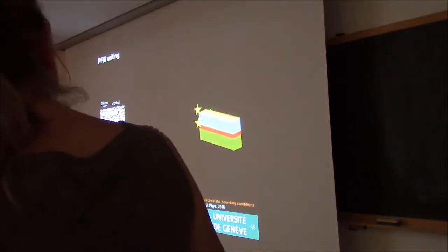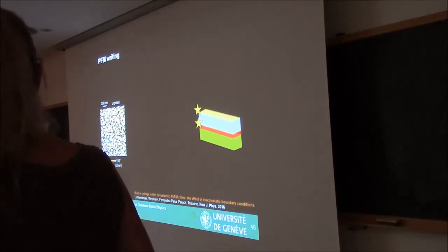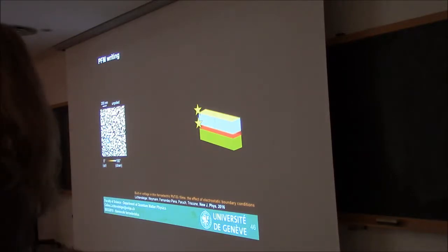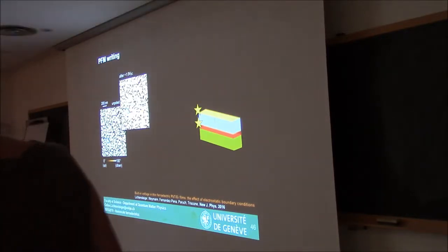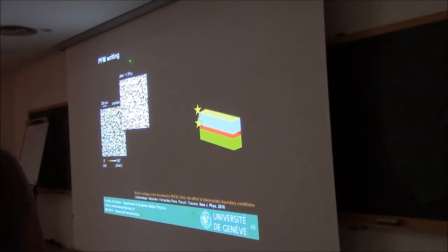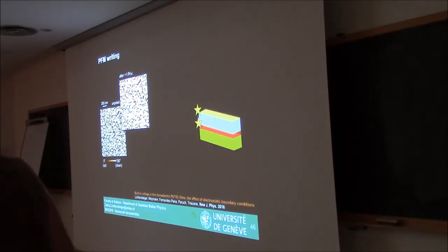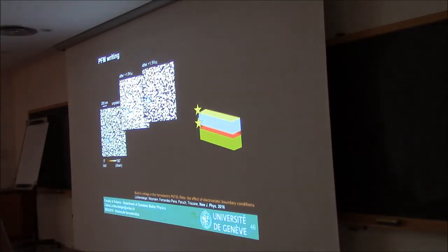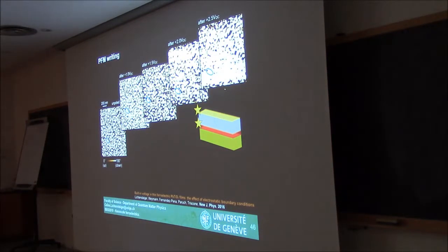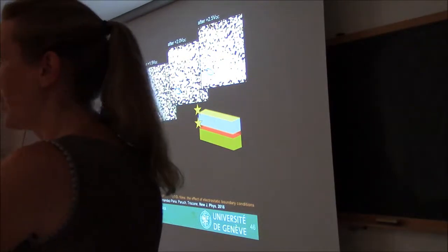Okay, then we looked at this 50 nanometer film with both the top and bottom STO spacer layer. So this is just a different scale of the image, but you see again these nanodots. And so what we did is that we used PFM to write. We scanned with the tip of the PFM over the whole area, applying a positive voltage, and then we scanned again just to read. And by applying a positive voltage, maybe you can start to see that the size of the domain is increasing even more until it kind of merges. So if you apply a larger voltage, then you can completely switch, again, locally, the polarization.